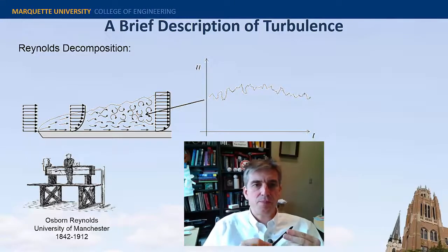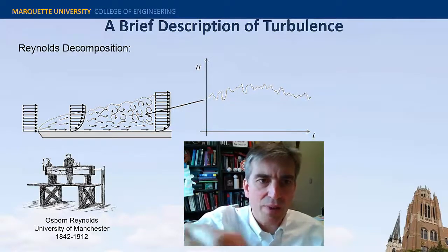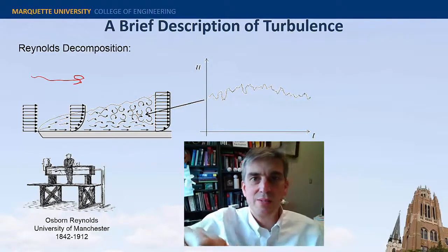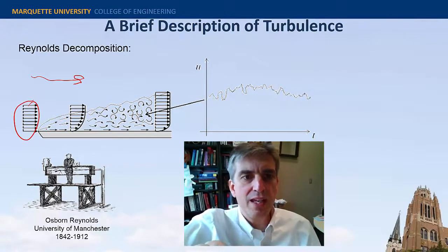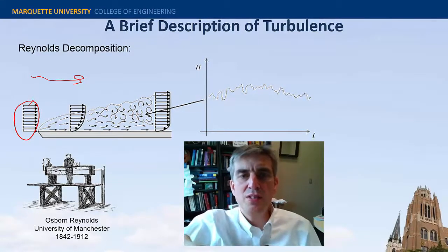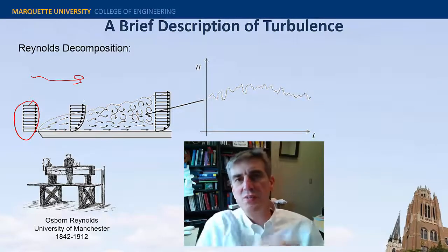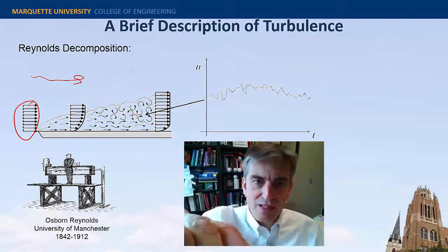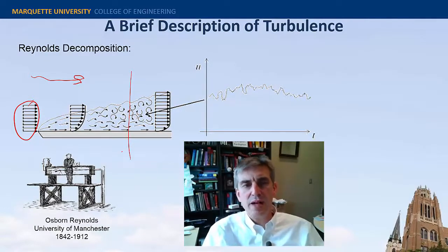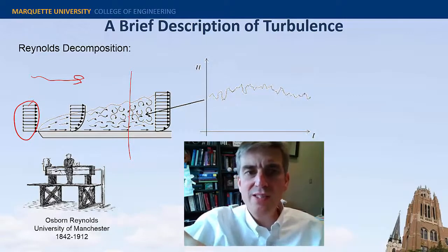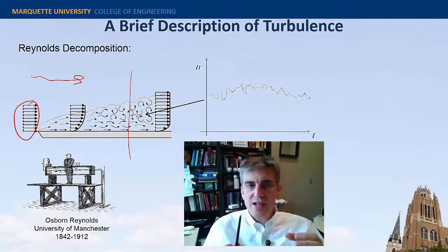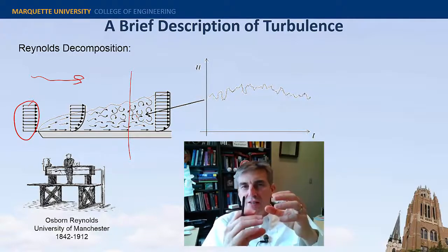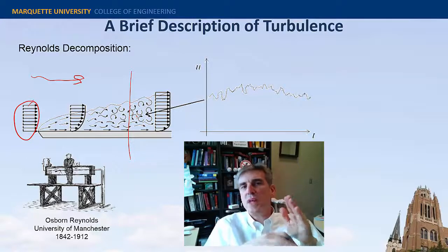So here's a turbulent flow over a flat plate, and maybe the external flow is laminar, right? So it's coming in here as a laminar flow. It attaches to the plate, and a boundary layer begins to form, and in so doing, there's a velocity profile. Now, if the Reynolds number is high enough, then within the boundary layer, you can get a transition to turbulence. So here's maybe a slice of that boundary layer through the velocity profile, showing that you've got turbulent flow, eddies and swirls, three-dimensional flow there inside the boundary layer. And eventually, as you get very close to the plate, it must relaminarize and go through that whole transition that we talked about earlier.